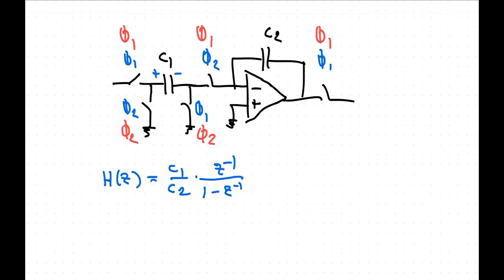Now what that is going to do is that during clock phase 2, you're shorting both sides of this capacitor to ground, so you're discharging it. And during clock phase 1, you charge it up to the same polarity here, but that current now flows into that and through that capacitor. So now it flows in the same direction in C2 as it did before.